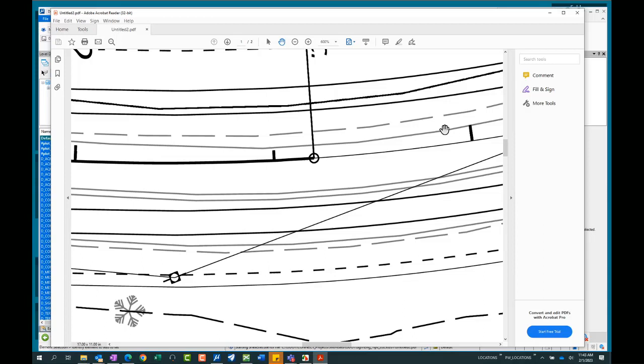Let's see. There's a question in the chat, and it says, I'm just going to read this to you all. If a designer drafter only has ORD in the future, they should always use ORD seeds, even if it's just for a plan sheet with graphics and no civil content. Answer is yes, that is true. So always use the seed file that has the name of the software that you will be using for it.